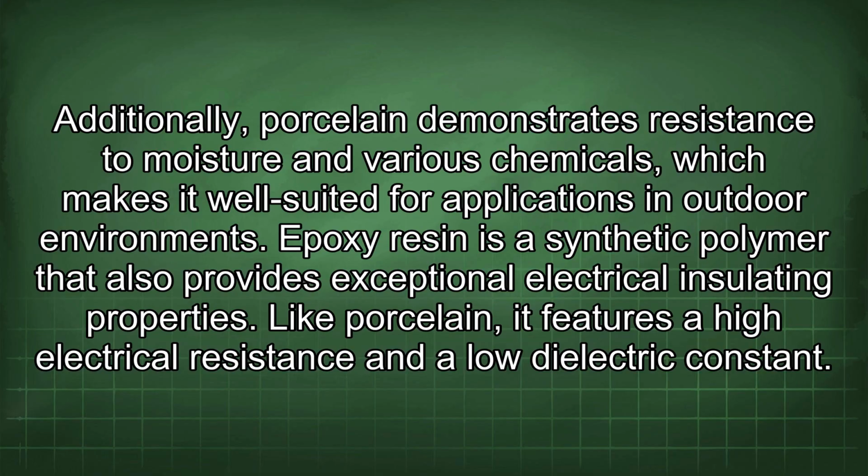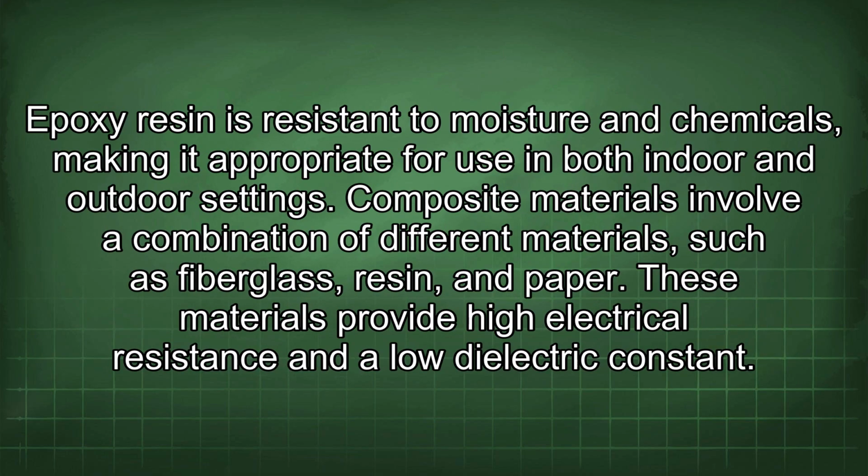Epoxy resin is a synthetic polymer that also provides exceptional electrical insulating properties. Like porcelain, it features a high electrical resistance and a low dielectric constant. Epoxy resin is resistant to moisture and chemicals, making it appropriate for use in both indoor and outdoor settings.